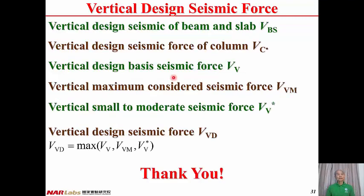From this lecture, we have talked about vertical design seismic force. Since the fundamental vibration period in the vertical direction for the beam and slab is different from the column, the vertical design seismic force for the beam and slab has to be computed separately from the column. Therefore, the vertical design seismic force of the beam and slab is different from the column.